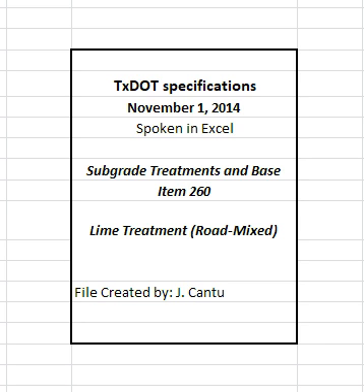4. Construction. Construct each layer uniformly, free of loose or segregated areas, and with the required density and moisture content. Provide a smooth surface that conforms to the typical sections, lines, and grades shown on the plans or as directed. 4.1 Preparation of subgrade or existing base for treatment. Before treating, remove existing asphalt pavement in accordance with item 105, removing treated and untreated base and asphalt pavement, when shown on the plans or as directed.